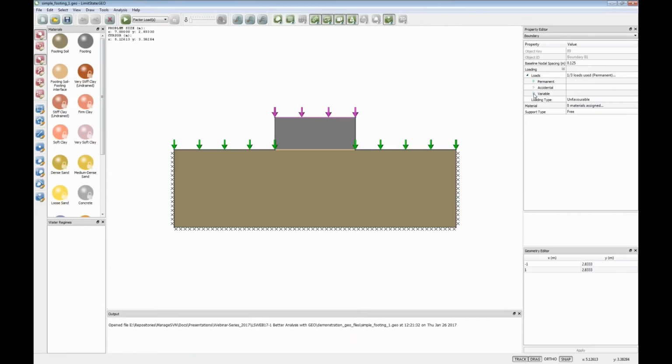Now this load is being applied as a unit load. We've actually got a half here, but the reason why I've put in a half is that this load's geometry extends, if we look down here, that line extends from -1 to +1, so it's 2 units wide. If we apply a stress of a half to that, that gives us a unit load of 1 kilonewton per meter. We have a property here called adequacy is true, and this is telling the software we want you to find out what you have to multiply this load by to cause collapse.